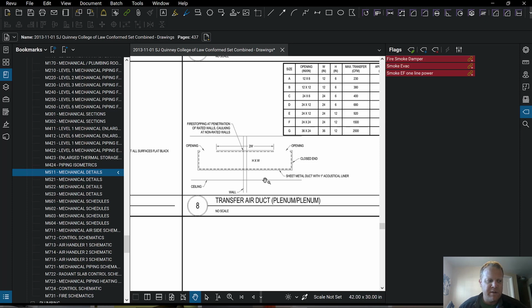It's like typical office building ceiling, right? Where above the ceiling is a plenum, and it's not drywall, right? It's that acoustical ceiling. And so air can transfer up into here, come into here, and go into the next space, right? So they don't have to have a return air ductwork in this room because they'll just put the return air ductwork on this side and it'll just pull air from this room too, right?